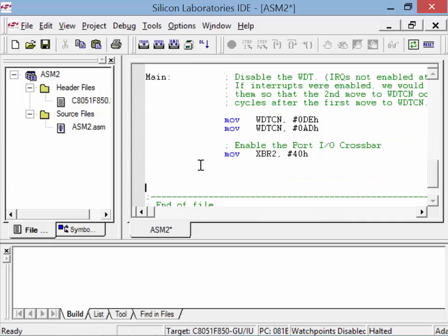This is where, and I'm going to put a comment in here, semicolon, insert your code here. So this is where your code would go if we're going to write an assembly language program. I'm just going to write a very simple assembly language program where I write to the accumulator, or A, and I'm just going to add 3 numbers, very similar to the example that we did earlier.